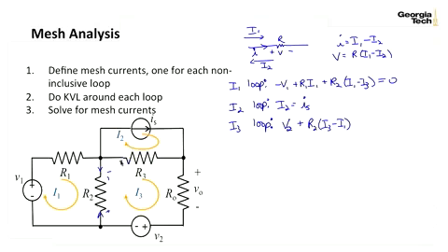And similarly up here, if I'm going in this direction right here, I want this voltage drop from here to here, then I'm going to be looking at that branch current there. So I've got R3 times I3 in the same direction, minus I2, which is in the opposite direction. And then coming around here, I've got one more term, and the Ohm's law on that term is R0 times I3, is equal to 0. And let's see, I've got 1, 2, 3, 4 elements across here, and I've got 4 terms in my I sub 3 loop, and that's it.